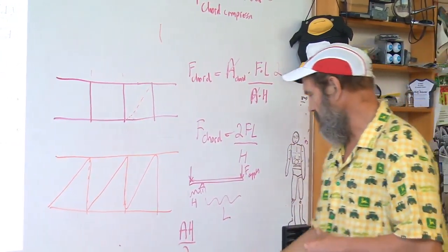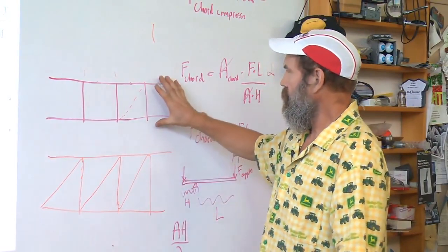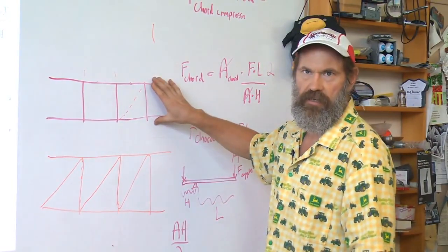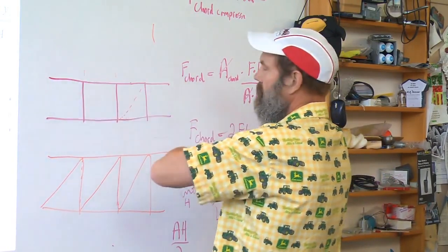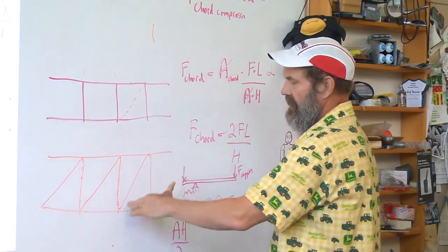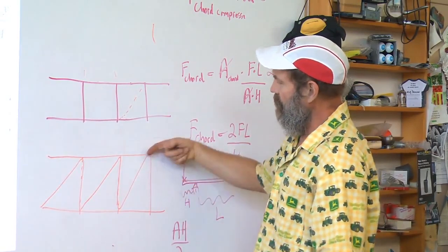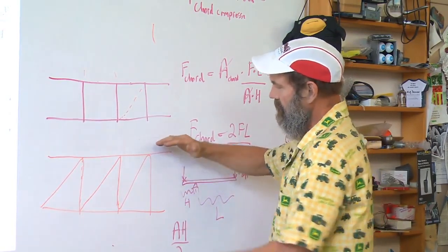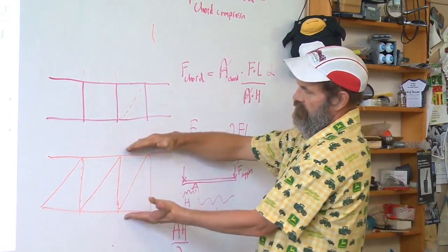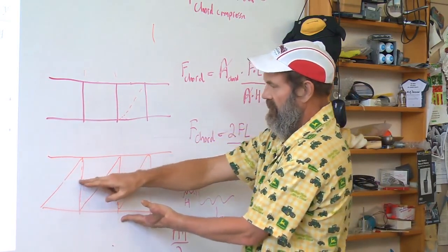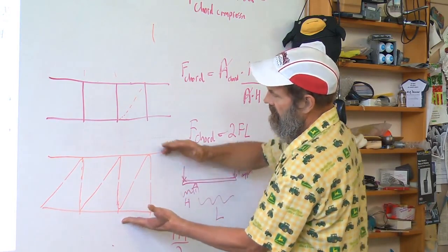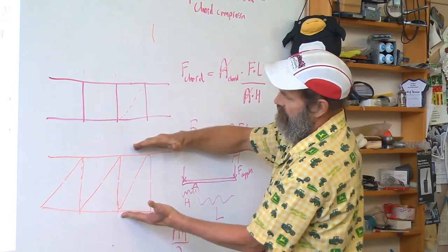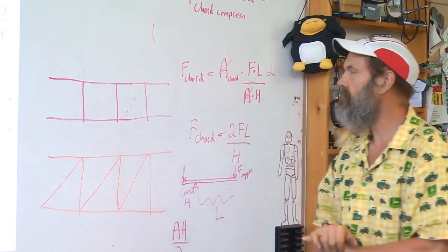Well, it turns out that if you go ahead and build one of these, you'll find that it really has no stiffness. You have to have the diagonal bracing in for the flow of forces to transfer. So what happens is you effectively have a shear through the middle of this plane, and it allows this structure to act as if it was an I-beam.